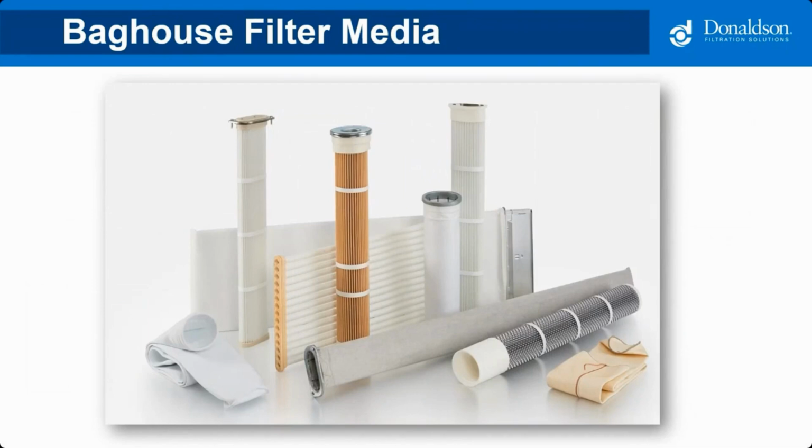Pleated bags are a one-piece design. They tend to be shorter in length and take significantly less time to change out. Keep in mind that not all baghouses can use pleated bags, but if you can use them, they are a great option for certain applications, such as abrasive dust.